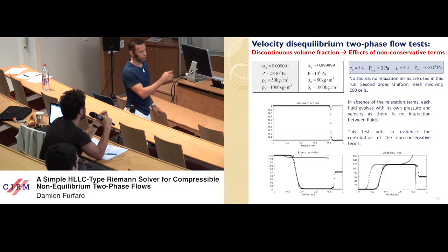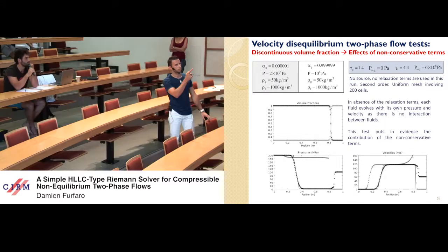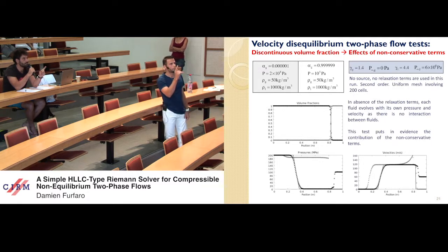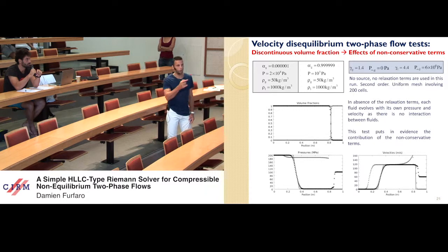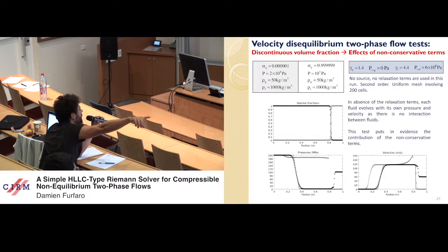At the initial state, the left chamber had a pressure validated for both fluids, but the liquid is nearly pure in the left chamber. On the right chamber, the same thing, but with atmospheric pressure, and this is a gas which is nearly pure. Those are initial states. Yes, but the pressure of the liquid is also equal to the pressure of the gas in this part. At t equal to 0, okay. But when the run goes, we can observe that in a given part of the shock tube, left or right, pressures are different between fluids, and velocities again. Yes, but you must have somewhere far right where both liquid and gas pressure are equal to the atmospheric pressure.